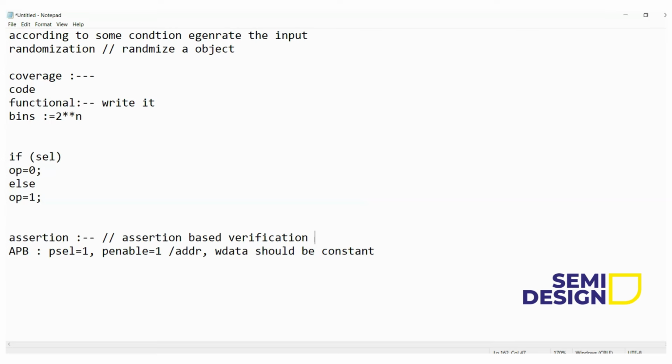Whatever delay we add with respect to gate may be different. But even with ideal simulation, we may need that. Whenever I send my first transaction, after 10 nanoseconds I should send my second transaction, and after 30 nanoseconds I should send my fourth transaction. I may have such a requirement. In ideal simulation also, we give some delay from transaction to transaction.